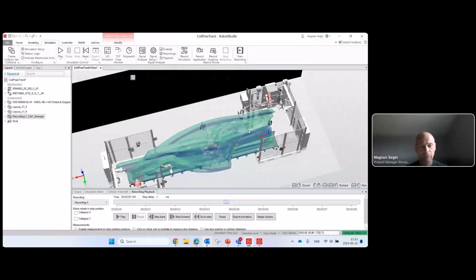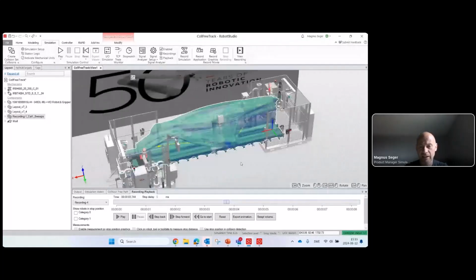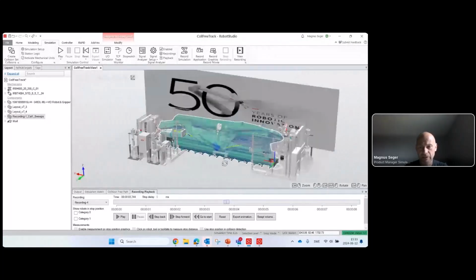The benefit of this, rather than reading your brochures and data sheets for how much stopping distance you need, is that it's way better, because this will tell you exactly, thanks to the virtual robot controller, how much space you need, and we can reduce the floor space and the footprint of the cell. So now we include tracks as well. Kind of cool, kind of handy in this setup.